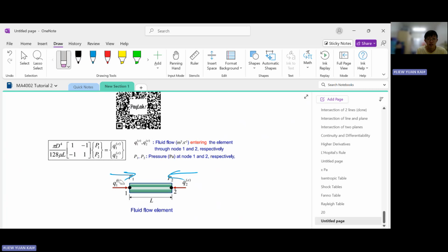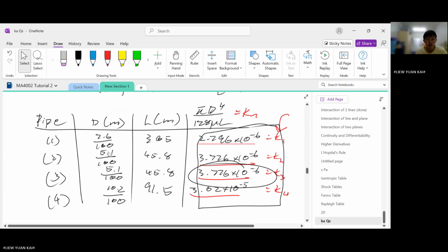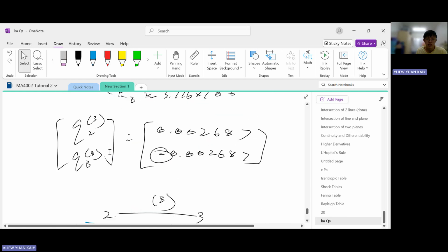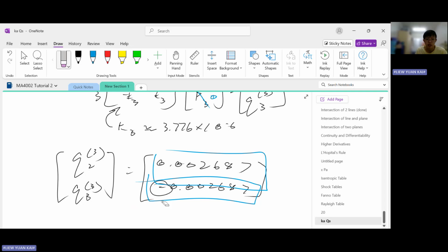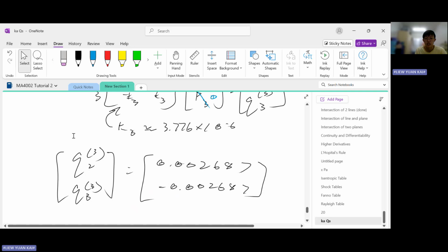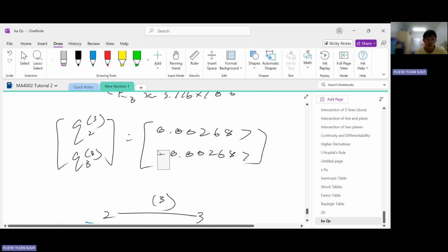In order to follow the real-life flow, in one direction, this one is the correct direction, but this one opposes the actual fluid flow. So when you calculate it, it should show up as negative. They're both the same magnitude but in different directions, because the formula is derived based on fluid flowing into the pipe on both faces, whereas actually one face is flowing in and the other face is flowing out. That's why there's a negative sign here.